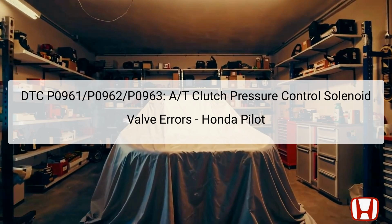This presentation focuses on the DTCs P0961, P0962, and P0963, which relate to the AT (automatic transmission) clutch pressure control solenoid valve A errors in the 2016 to 2022 Honda Pilot. These error codes indicate specific issues with how the pressure control solenoid operates, which can significantly affect the smooth operation of the transmission system.